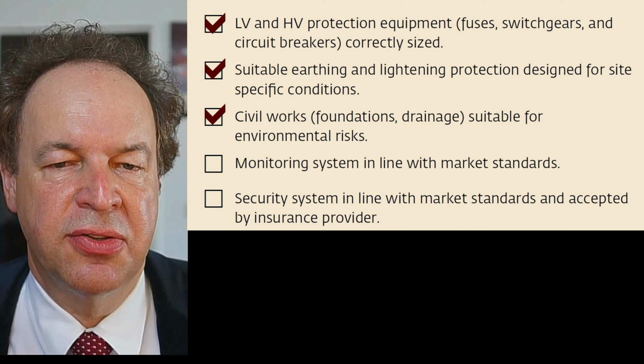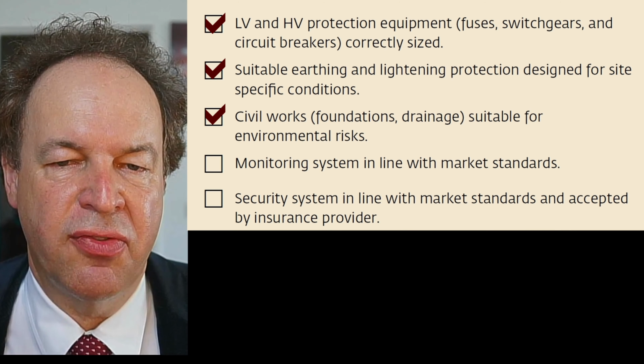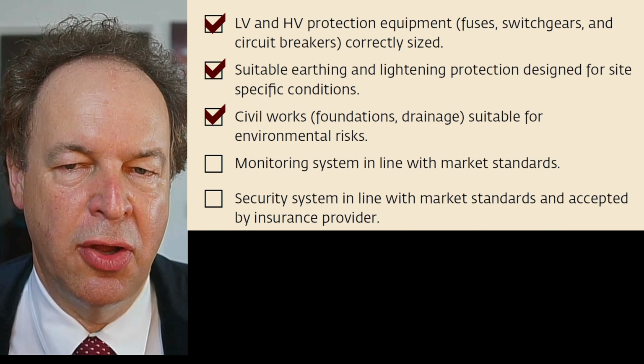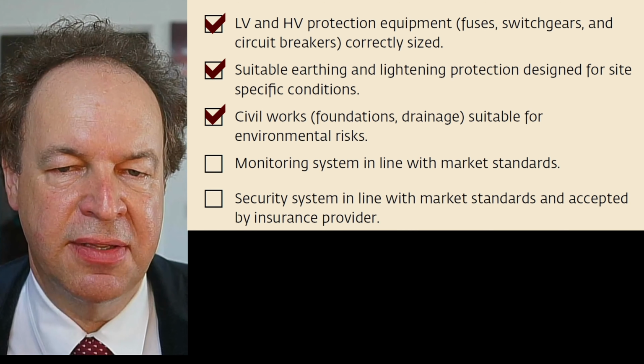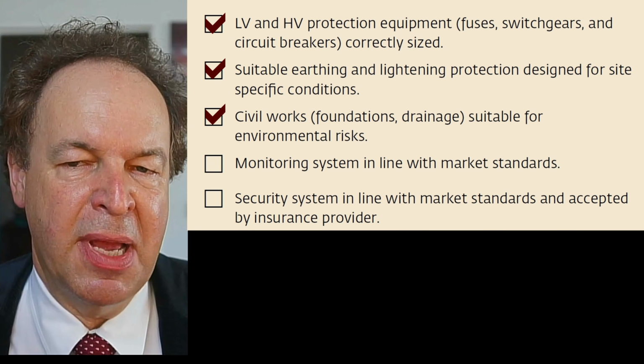Civil works, so that's the foundation and the drainage for rain and so on. You have to make sure that no water enters the hut where the inverter is and so on. So you have to make sure of that. And depending on the local conditions, if you are in the desert, you have fewer problems. But if you have an area where you have a monsoon period, this can cause some serious problems.